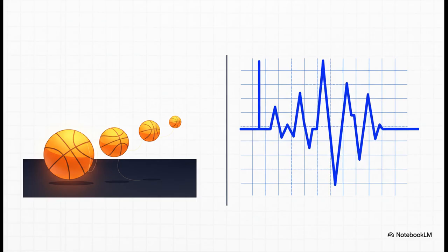When you drop it, it doesn't just hit the floor and stop dead, right? Of course not. It bounces a couple of times, each one smaller than the last, until it finally settles. That is exactly what's happening inside a switch with the electrical signal, and our device has to be smart enough to ignore all those little bounces and just count the first thud.